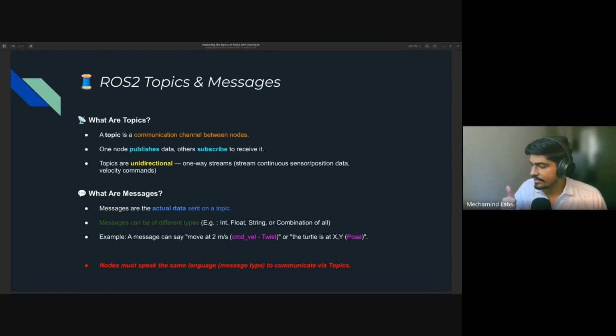We have to send it in geometry_msgs Twist type. Only then we can send a velocity command. We looked at that if we want the current position and orientation of the turtle, in which interface does the topic interact? It interacts in the turtle1/pose topic, turtlesim/msg/Pose message.